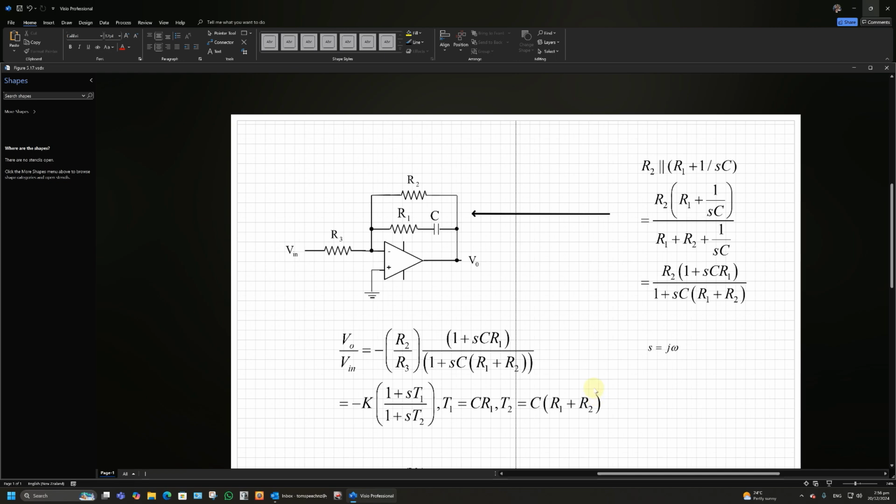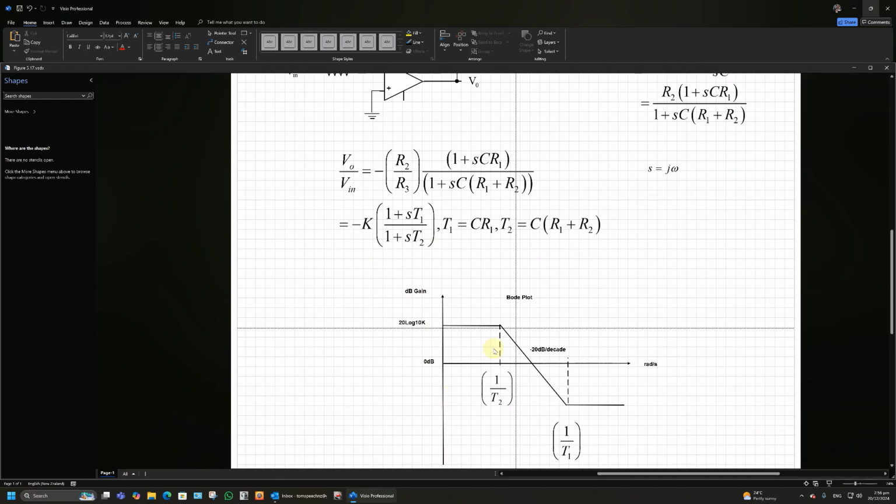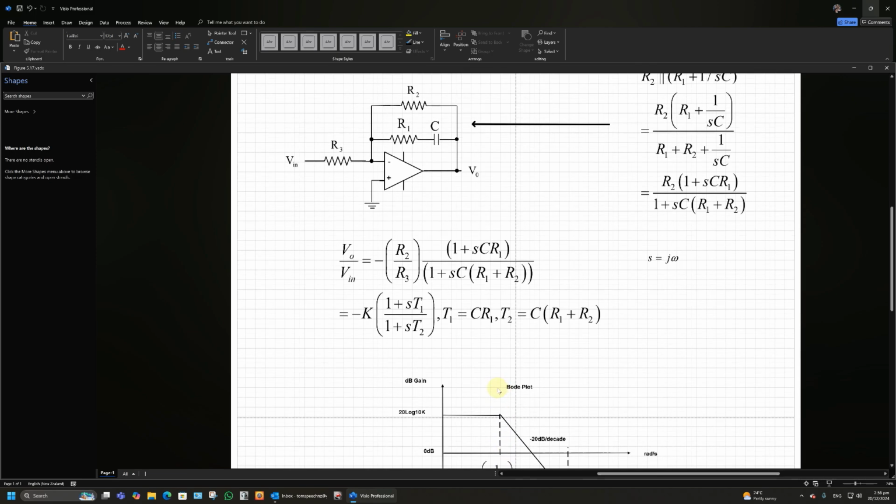But nevertheless, it should be able to work it out for itself if it knew a basic principle that for this kind of simple circuit, where you feed back into the summing junction here, the voltage gain is this whole thing here divided by this thing here, and it doesn't matter what you put in there and what you put in there, you can work out that transfer function. So you could put a series capacitor in there, for example, work it out again and work out how it changes and plot the frequency response. This is the asymptotic frequency response, of course, not the exact one. The exact one's got a curve there at the cutoff frequency, at the lower cutoff and the higher cutoff. And I've missed the phase out deliberately because I don't want to make it too complicated.